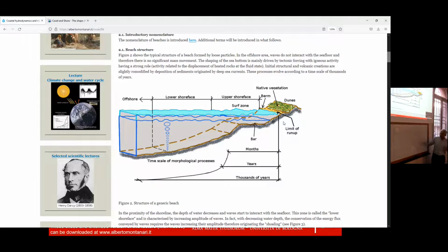And the activity of the waves, the length of the run-up, is longer. So the result of these two changes, the breaker line that goes back and the run-up that becomes longer, is typically a shift of the berm that is moved a bit landward and becomes a bit higher. And this is a seasonal evolution.